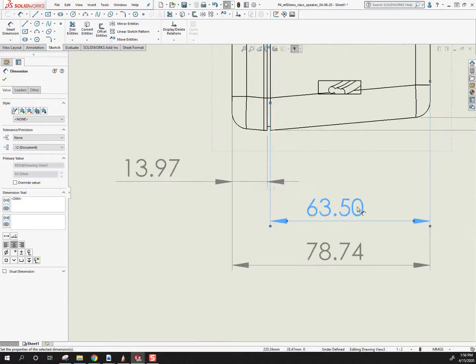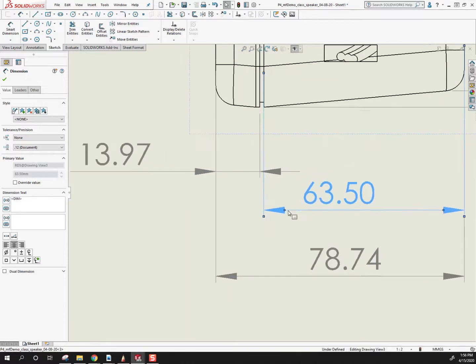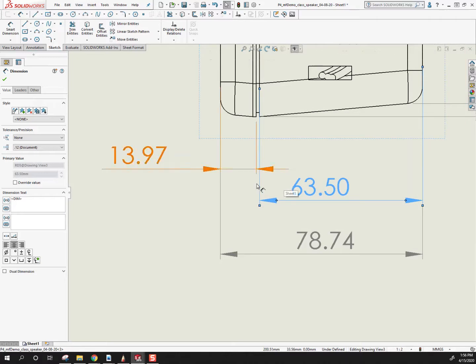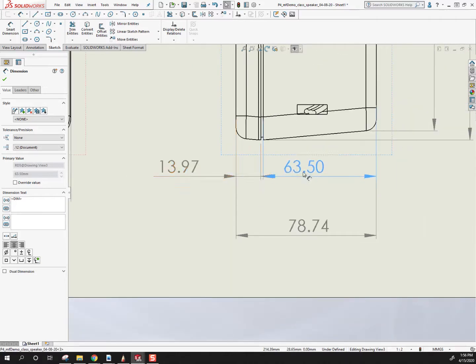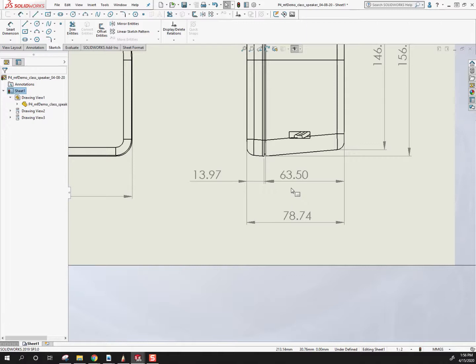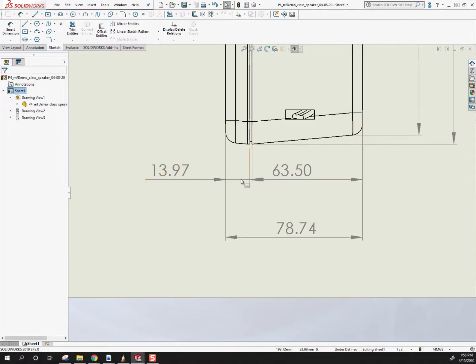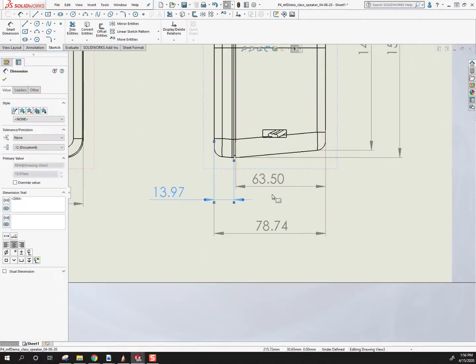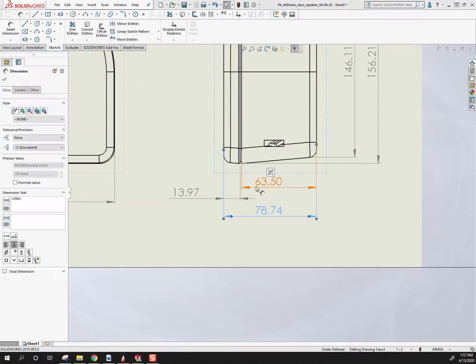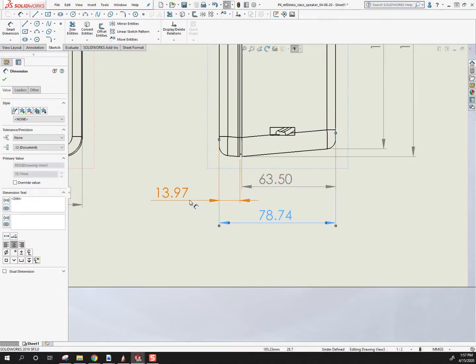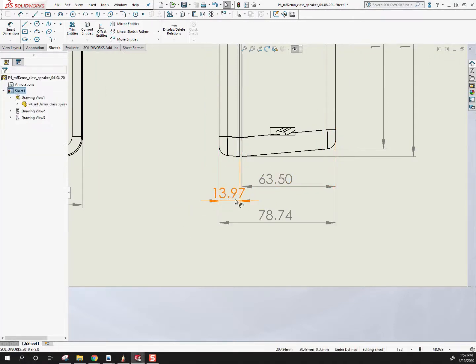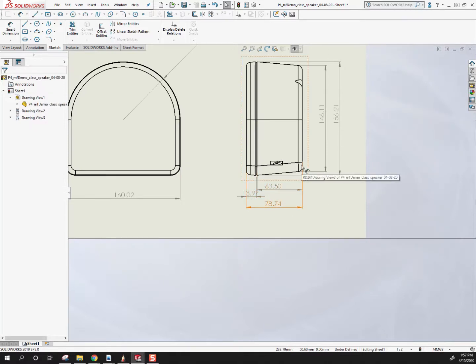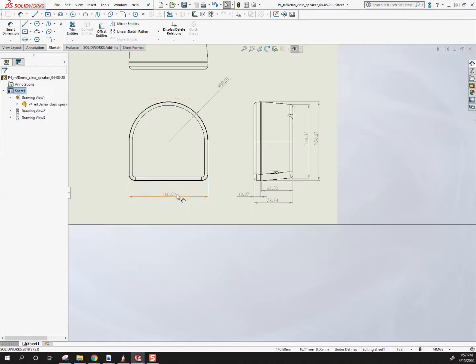Here, something like this I won't take off points for because you're technically doing the right thing. I think if you do something like this, I probably wouldn't take off points, but I would probably circle it and say that's confusing. So you want to offset these. Of all the options, this is the best practice here. It's staggering the 3 like this. Something like this, that's not ideal either. That's not good. Dimension drawings are important. You will do one at some point in your career.